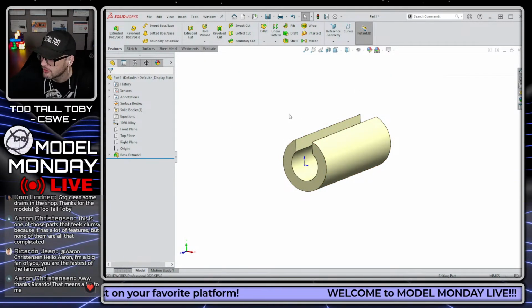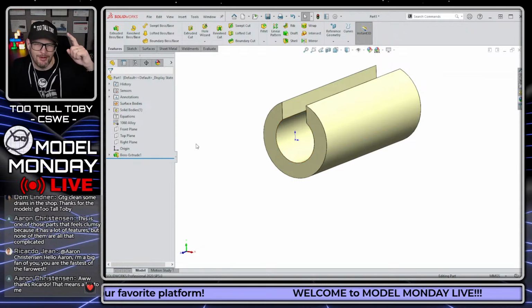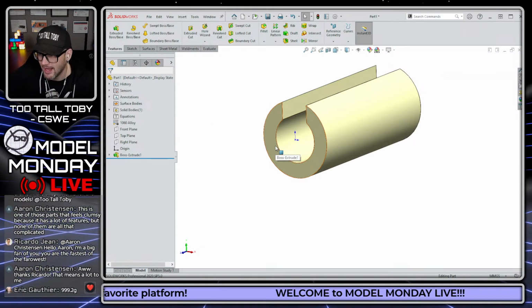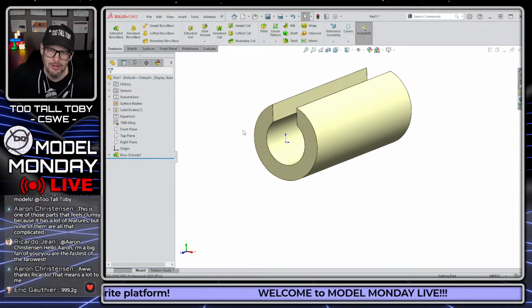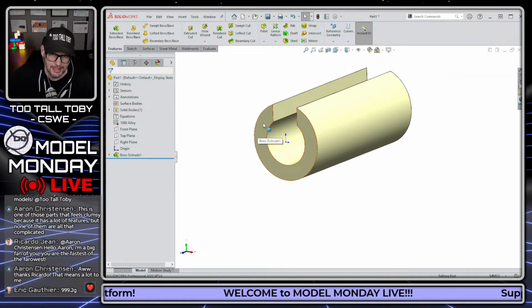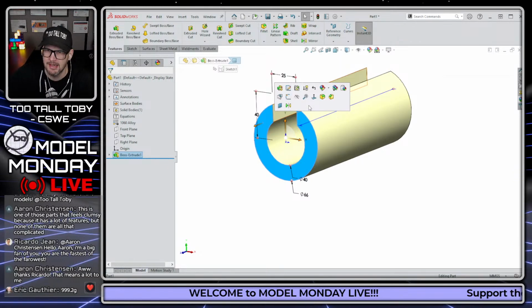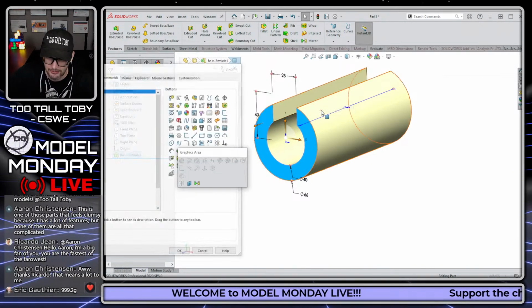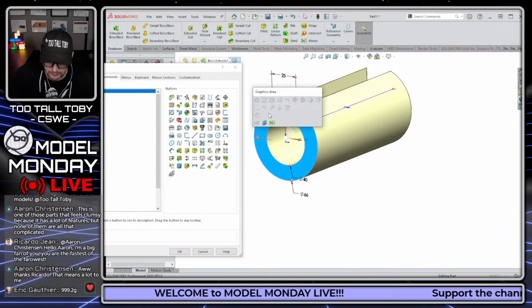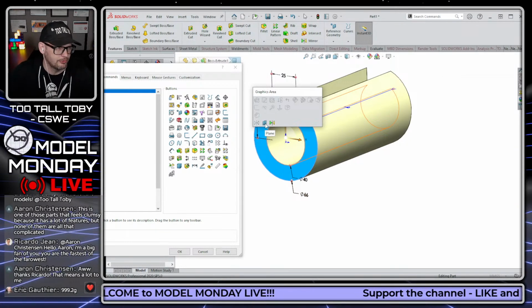For my second feature, I'm going to create a new plane here. Now, I haven't made a power move on this yet, but I've got to give a huge shout out to Andre, one of my students, who showed me this awesome shortcut for plane creation. That shortcut is simply click on the face of something and then right mouse button in your context toolbar and choose customize, and then add planes here. Oh, it didn't zoom in. Add planes here on your customized toolbar.